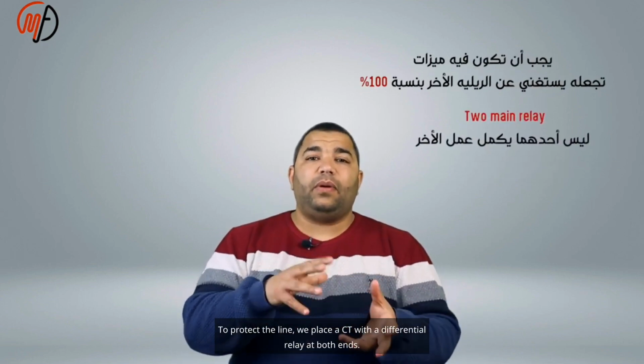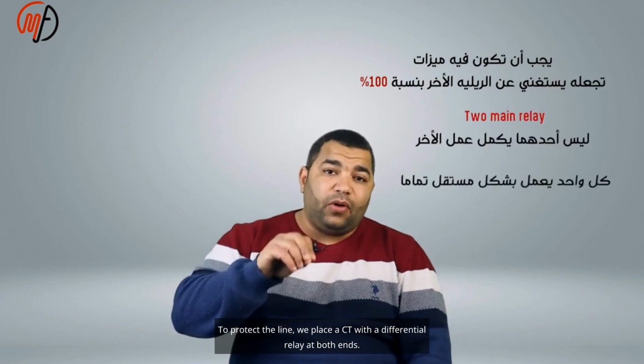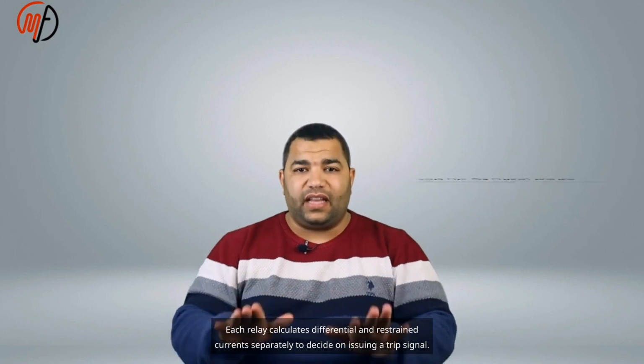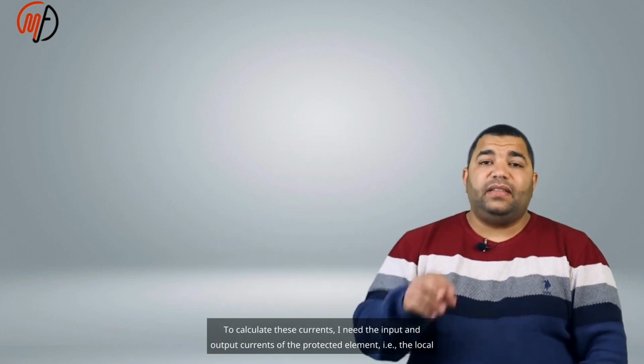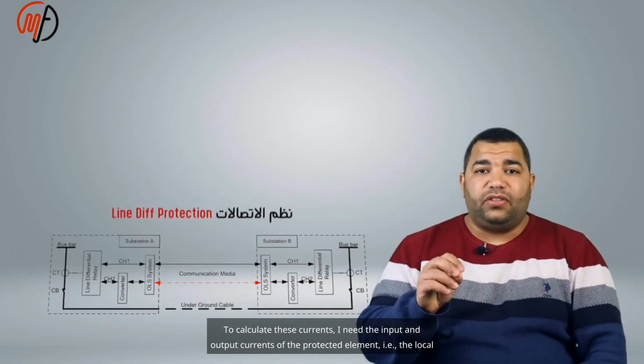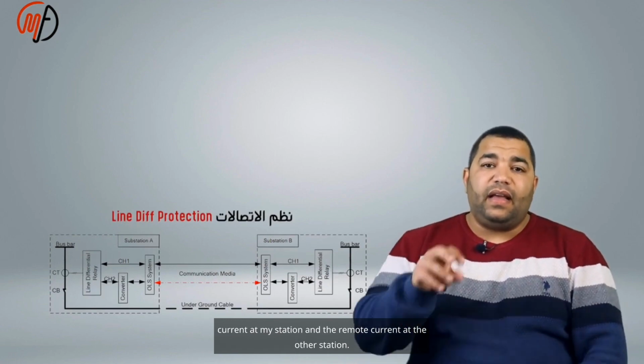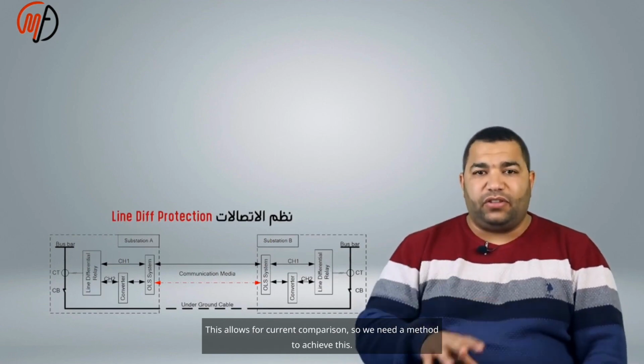To protect the line, we place a CT with a differential relay at both ends. Each relay calculates differential and restrained currents separately to decide on issuing a trip signal. To calculate these currents, I need the input and output currents of the protected element, i.e. the local current at my station and the remote current at the other station. This allows for current comparison, so we need a method to achieve this.